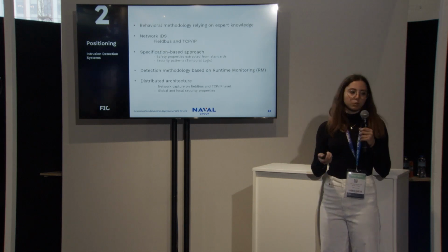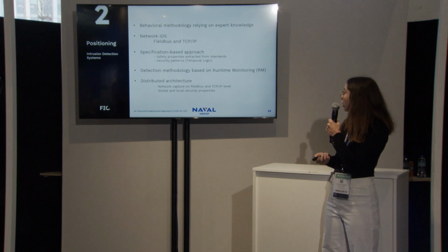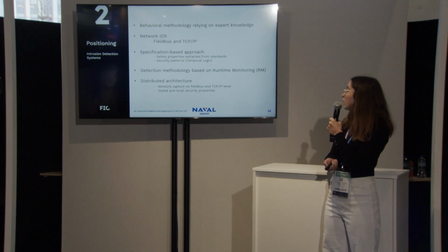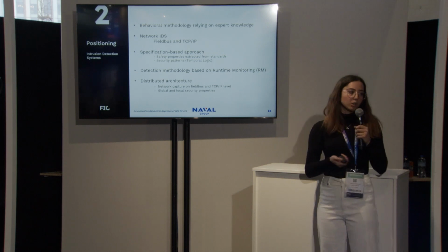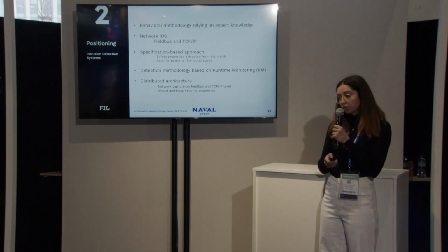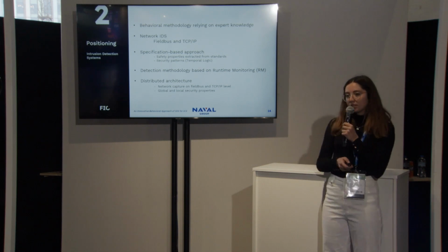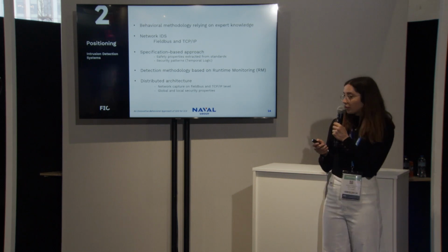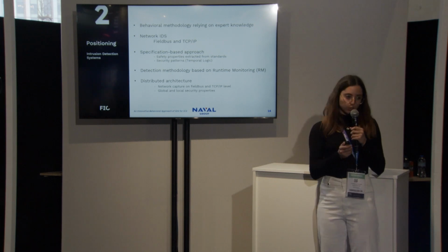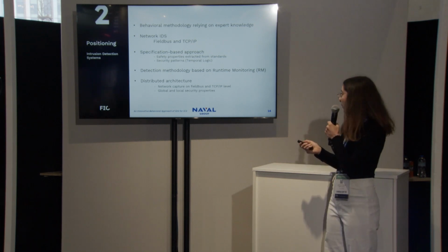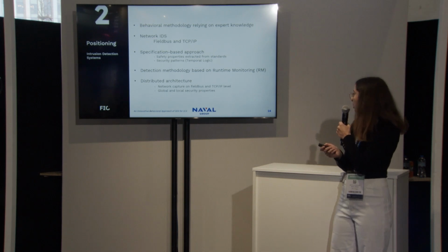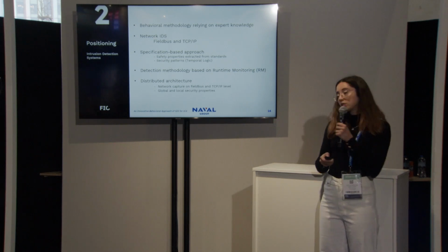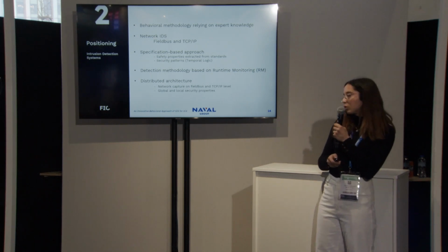So if I want to synthesize what we do, we work on behavioral methodologies relying on expert knowledge. We have a network IDS, so we work both on field bus and TCP/IP networks. We have a specification-based approach that I will detail in the next slides. The detection methodology is based on results from runtime monitoring that I will also develop. And we work on a distributed architecture. So we have a network capture both on field buses and TCP/IP networks, and we work on global and local properties.